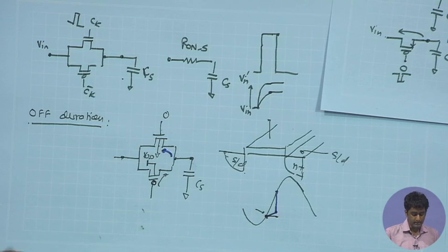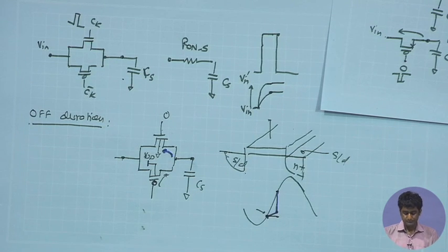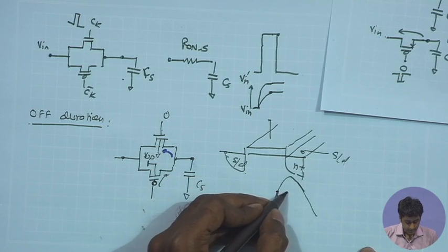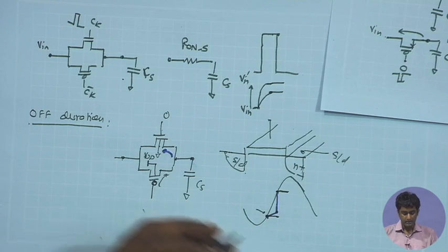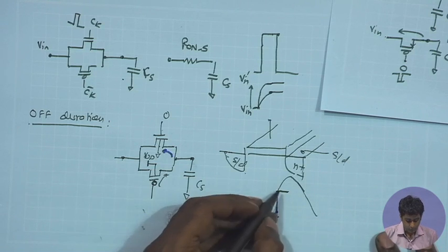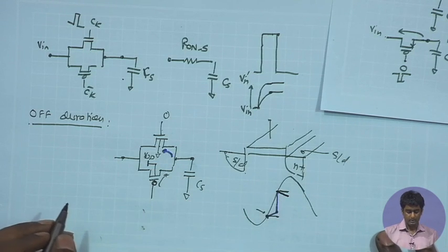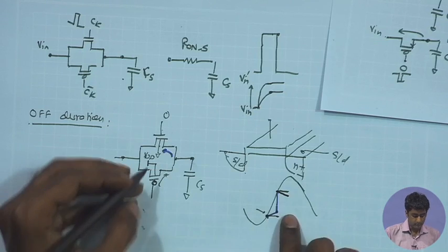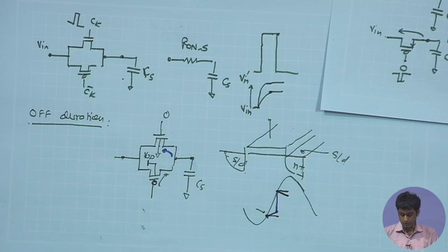And that would imply that as compared to the sample value, we would expect that ideally this sample value should once again remain flat, but rather than remaining flat, it will go down a little bit, right, and that will be determined by the leakage current, how much it droops.